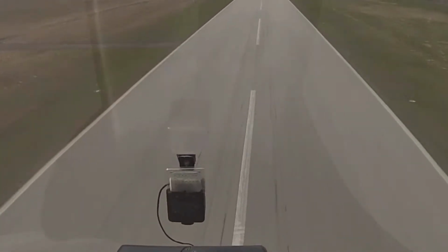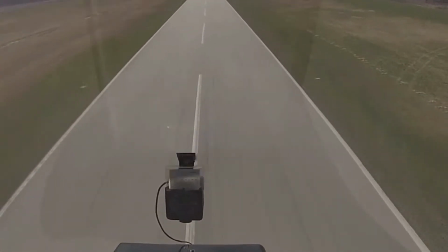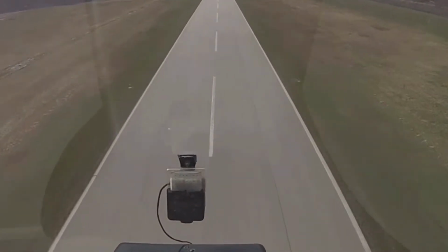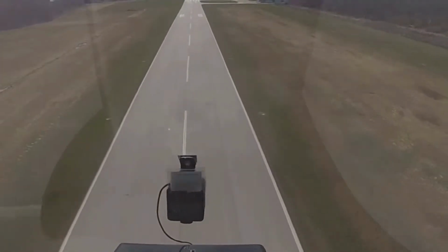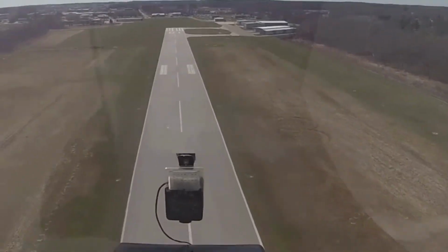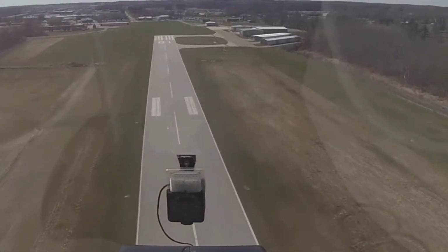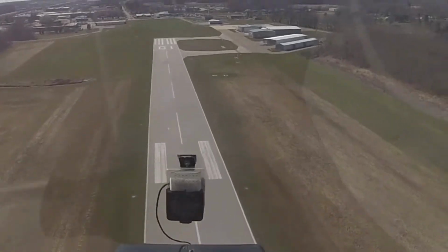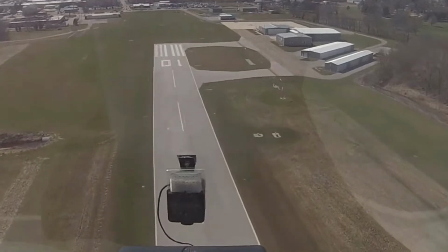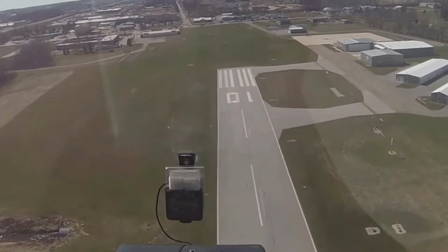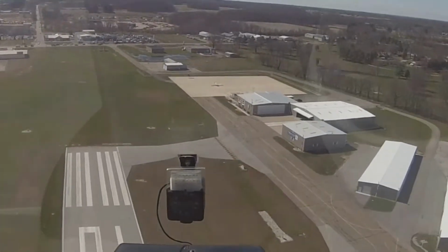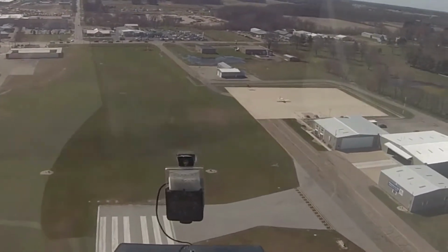Now I've got some airspeed. If the engine would quit, I could flare and get it on the ground. I want to get to 60 as soon as I can, which today is easy. Boom, I'm at 60 already. I have almost a 500 feet per minute climb. Now if the engine quits, we have a good chance at a successful outcome, getting the thing on the ground and getting out and walking away. If you pull too much power first, put it nose low, and you have an engine failure, that could be ugly. If you go too high without getting forward airspeed and you lose the engine, that could be ugly too.